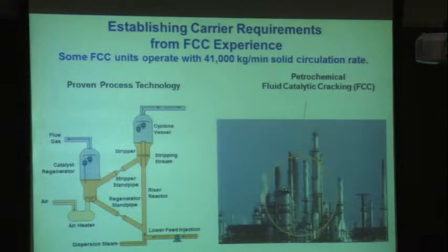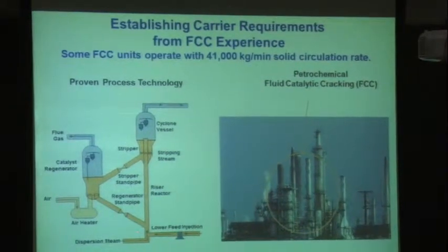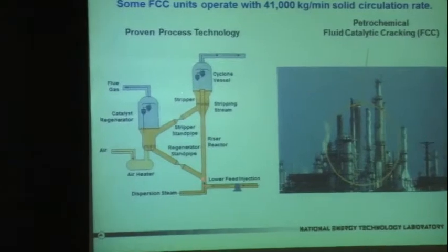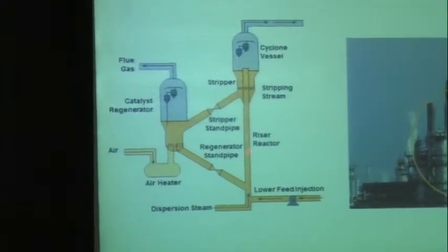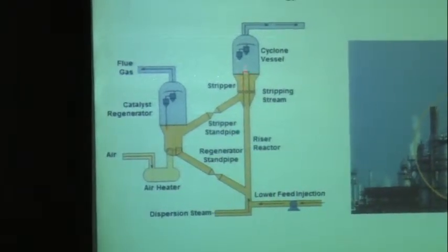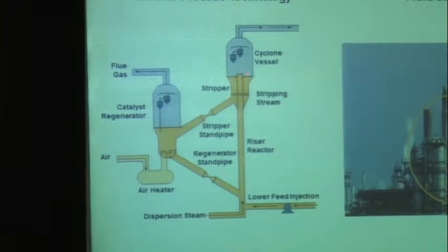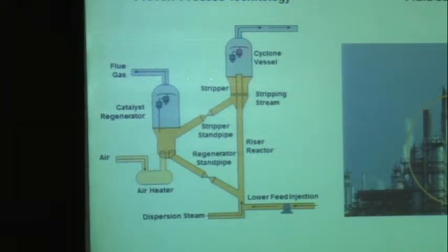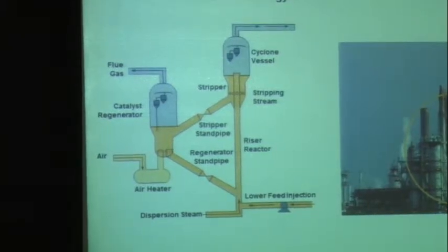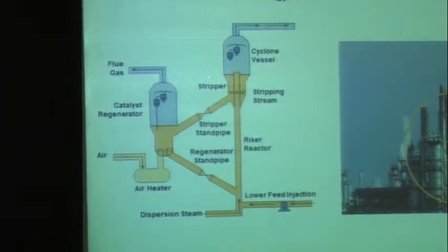These are commercial processes that already exist, and they take solids, and you put in the hydrocarbon that you're trying to process with some steam, and it basically coats up on solid particles. They go flying up as you heat that stuff up. You strip off the lighter hydrocarbons, and then the coke, or the solid carbon, comes back down with the material along this leg, and you basically burn it off. That's how you change the C to H ratio when you're doing hydrocarbon processing.